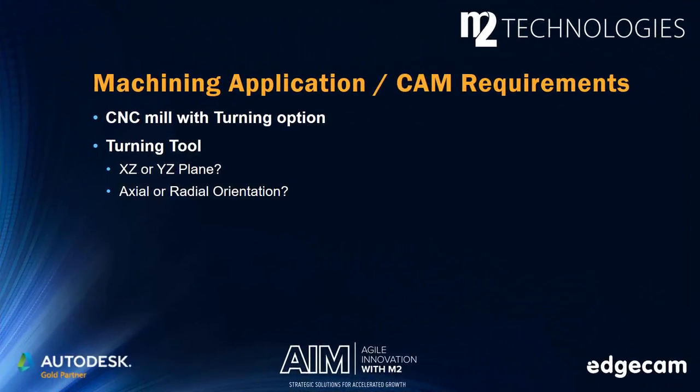This machining application can be done in multitasking CNC machines equipped with turning capability. The CAM requirements to add turning begin with selecting a turning tool from the tool database, selecting whether to machine in the XZ or YZ plane, and determining whether the tool orientation to the workpiece should be axial or radial.